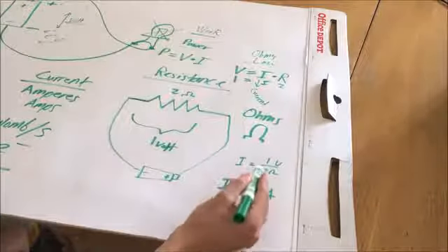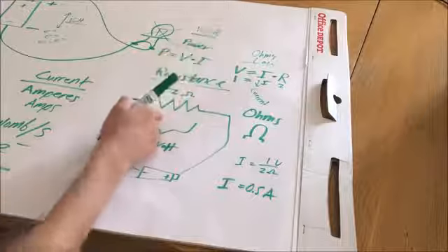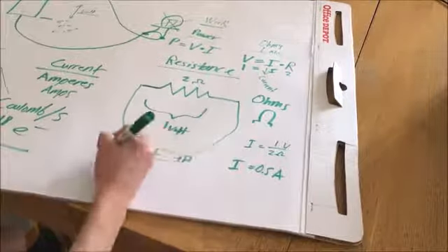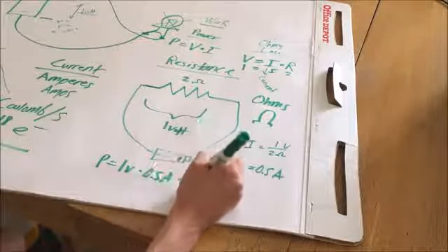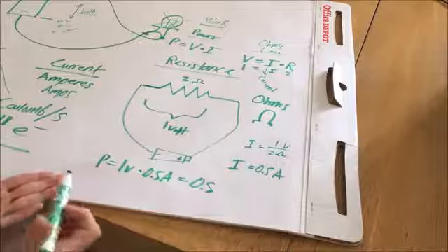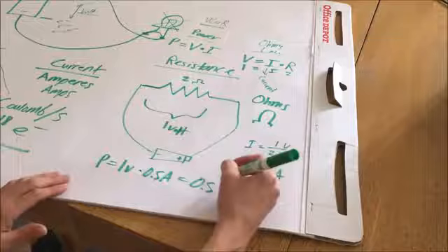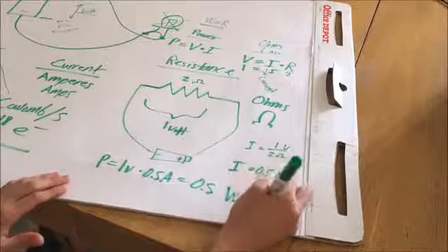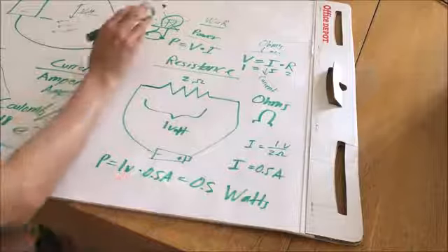So to use the example that we just had, we know the voltage across the circuit is 1 volt, and we calculated that the current across the circuit is half an amp. So the power would be 1 volt times 0.5 amps, or 0.5, well, what do we measure power in? What is your coffee maker or your space heater rated in? Well, it's rated in the watt. And the watt is a unit of power. That is a unit of work per time.